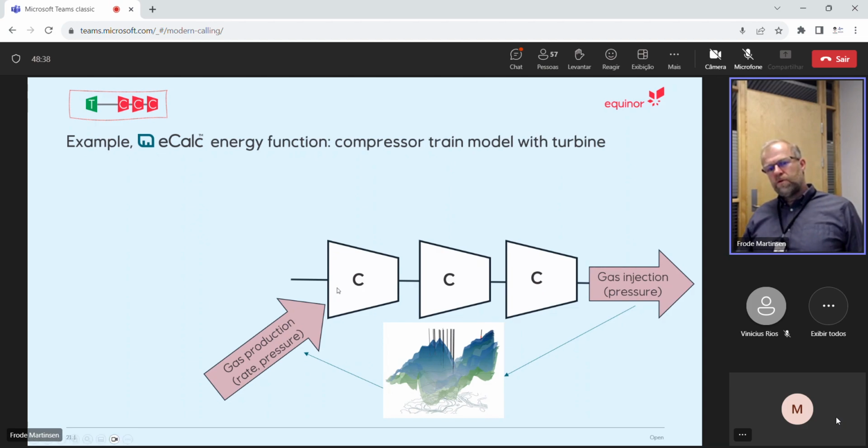And that increases not only the pressure, but the temperature on the outlet. And the temperature is typically a problem because the flanges, the steel quality on the downstream side here, can't take temperatures above, let's say, 140, 150 degrees. So at a certain pressure ratio, you have to cool it before you put it into the next one. That's what we had on the sketches earlier on.